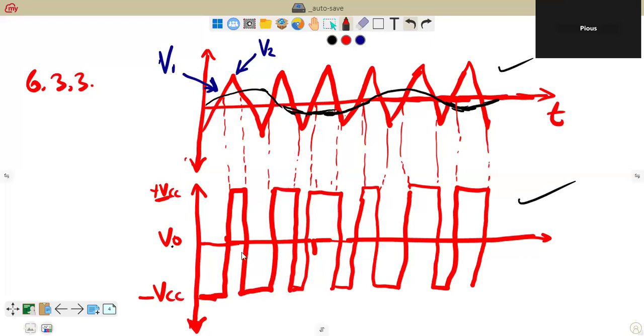This reaction is clearly shown on the output waveform. So the op-amp is behaving as a two-state digital device, with the output voltage switching from high to low in this form. That's why the output waveform looks like this. It is often used as a comparator to compare voltages; that's the purpose it is normally used for. I just mentioned that out of interest, but the question only wanted the input and the output waveform as we have indicated them there.